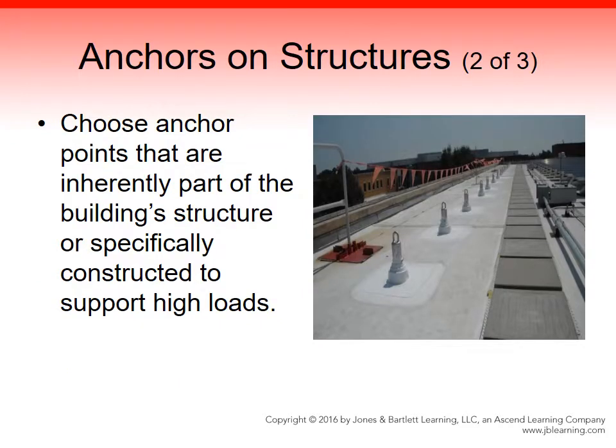Choose anchor points that are inherently part of the building's structure or specifically constructed to support high loads. Some examples are structural columns, projections of structural beams, supports for large machinery, and stairwell support beams.